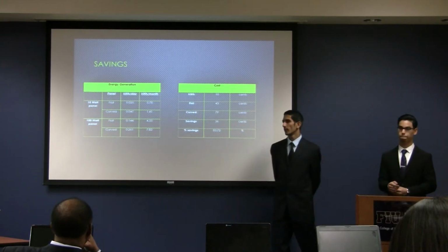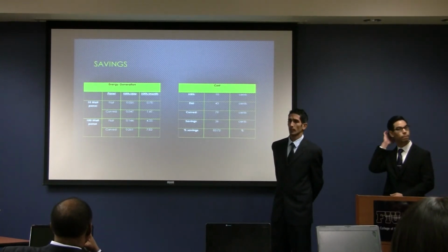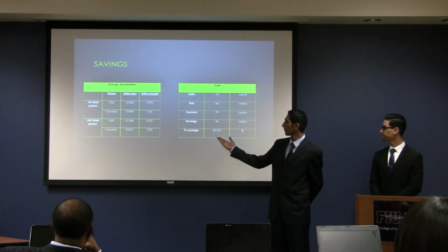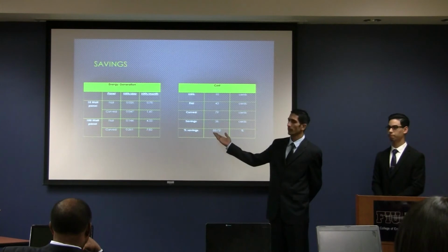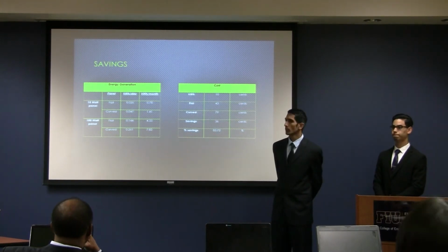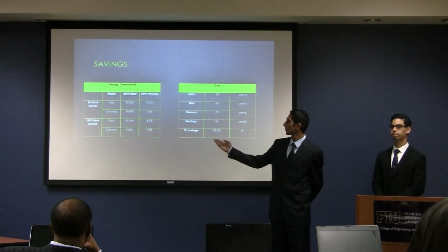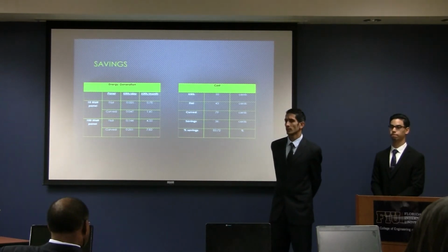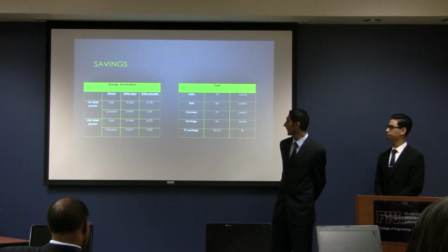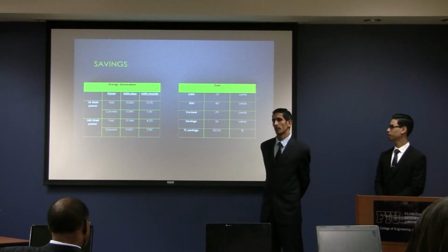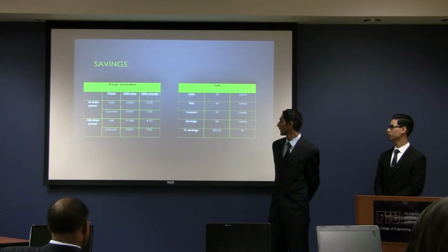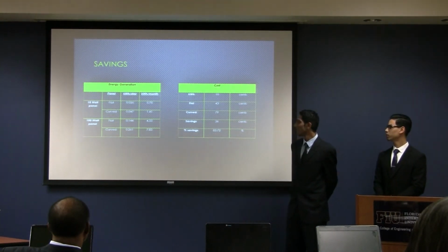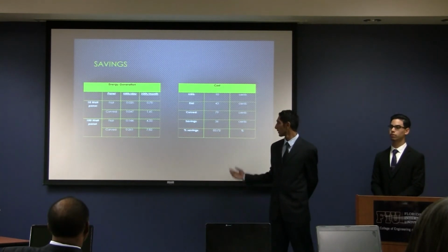Based on the energy generated by the flat panel and the curved panel, the panel is rated at a maximum of 18 volts. We did the conversion to raise the scale to a 100 watt panel, which is available commercially. And furthermore, to do the cost analysis, we used the pricing available from FPL, which is 10 cents per kilowatt-hour. If you do the cost analysis, you can see the curved panel saves about 83% compared to the flat panel.